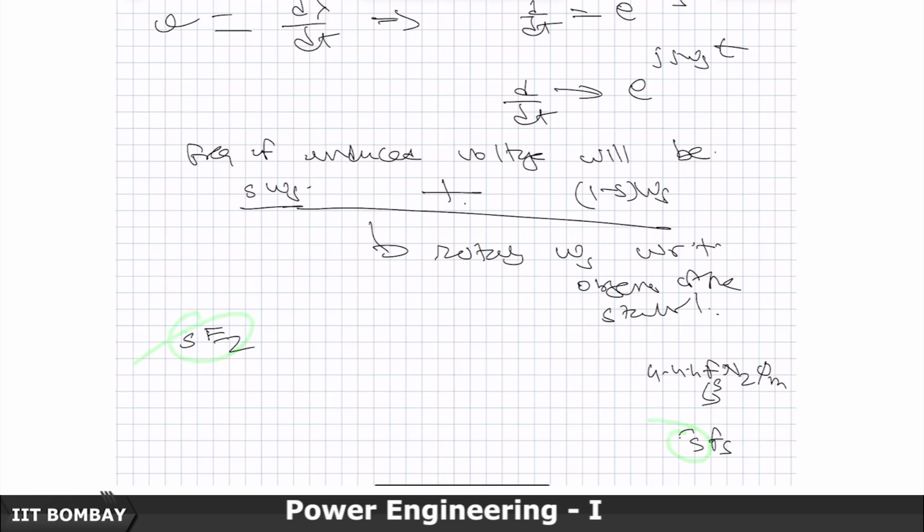So, therefore, the voltage induced in the secondary winding will be S times E2, and the effective reactance seen will be S times X2, where X2 is the leakage reactance of the rotor winding at the synchronous speed. Then at slip S, the only reactance seen is S times X2, because X is omega L.